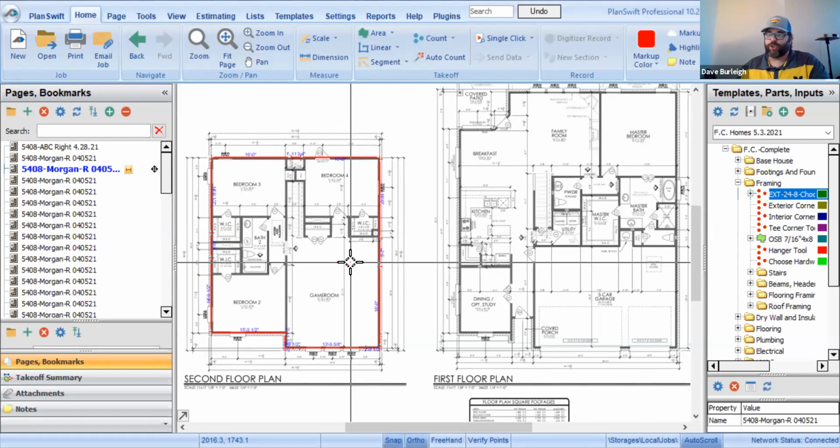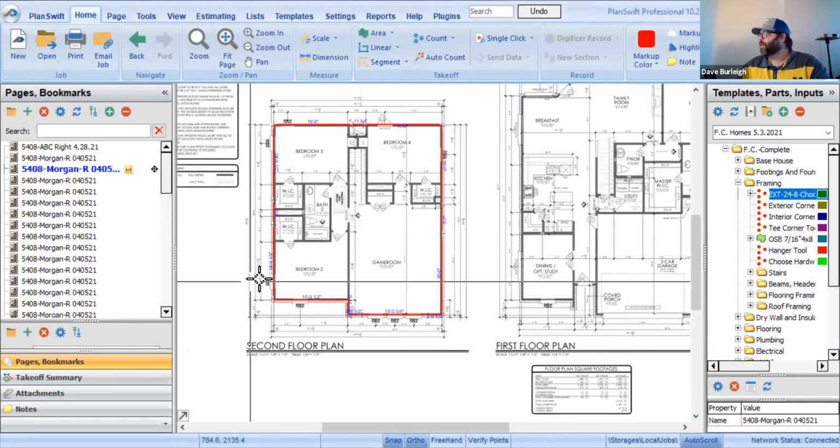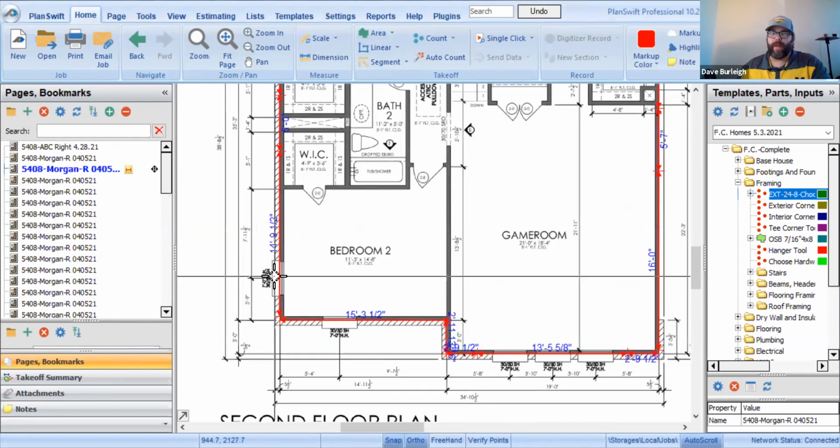So what we converted to is now we think of the plan as if we're building it in a factory. So we go through and outline what all of our dimensions are based on what our maximized framing is. So for example, on a 16 on center, 16 foot is the best we can ask for in a stick frame environment.